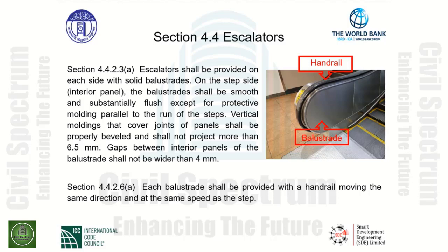We have specific requirements, one being section 4.4.2.3a, escalators shall be provided on each side with solid balustrades. On the step side, the interior panel, the balustrade shall be smooth and substantially flush, except for protective molding parallel to the run of the steps.